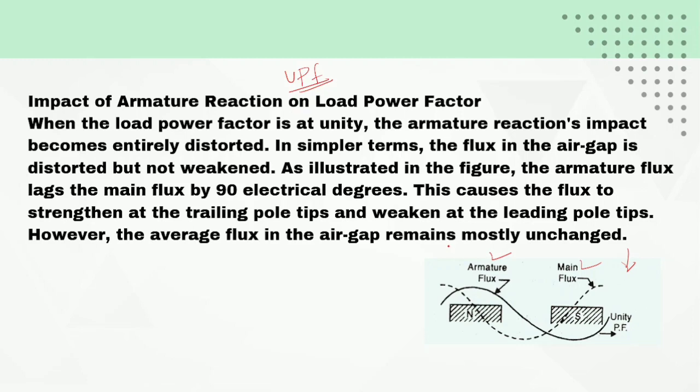The effect will be different for different power factors. Based on this diagram we can easily analyze the impact of armature reaction on the load power factor. When the load is of unity power factor, the armature reaction impact becomes entirely distorting, meaning it only creates disturbance but does not reduce the armature flux.